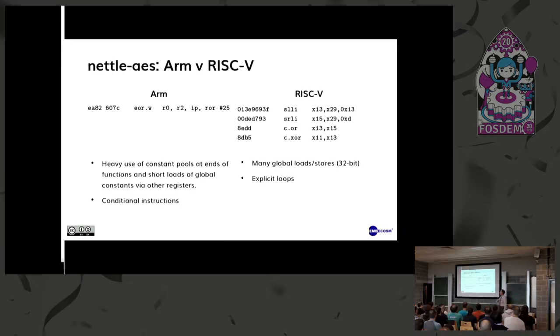So what you do in 32 bits in ARM, you need a total of, if I've added that up right, 96 bits in RISC-V. Okay? And that structure comes up quite a lot in that cryptographic code. That's why ARM actually comes out well on the cryptographic stuff. That's something to bear in mind when looking at instruction set extensions for RISC-V. We can't do much about that in the compiler. That's an architectural thing. Okay? So sometimes the answer you'll get given is you can't fix this, but other times you do.